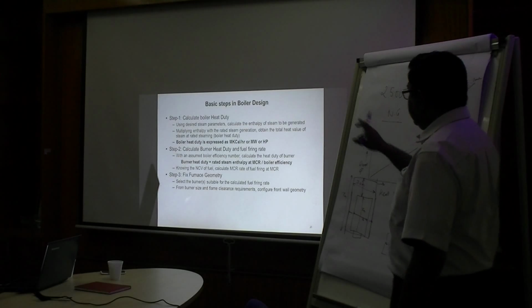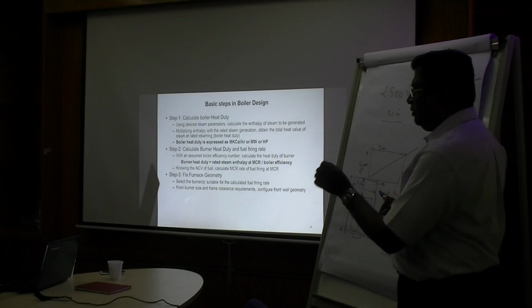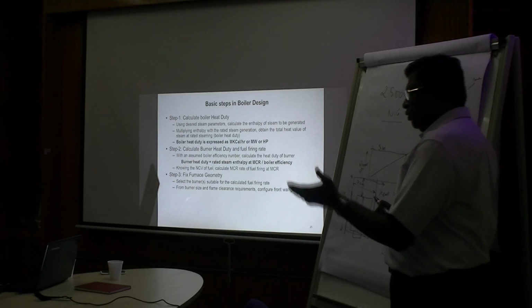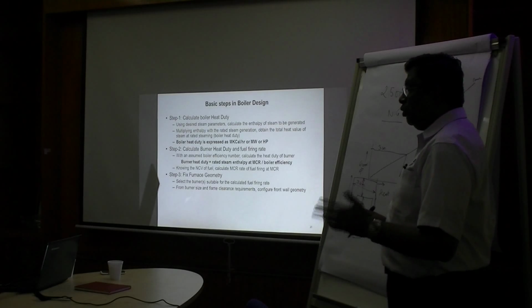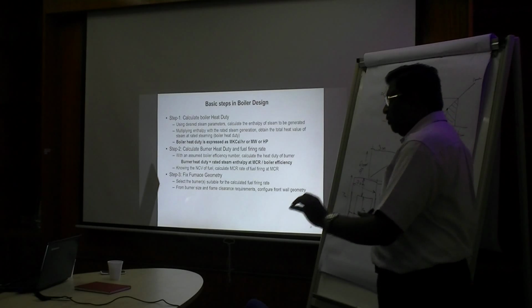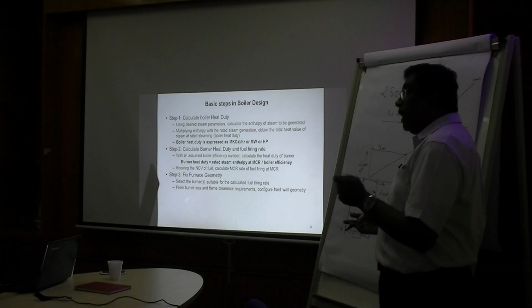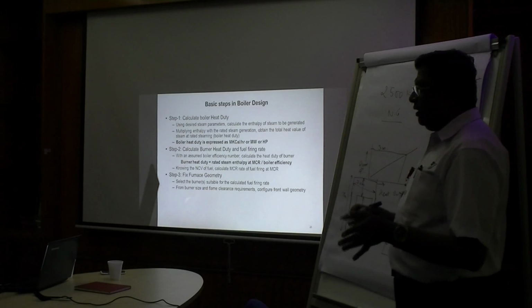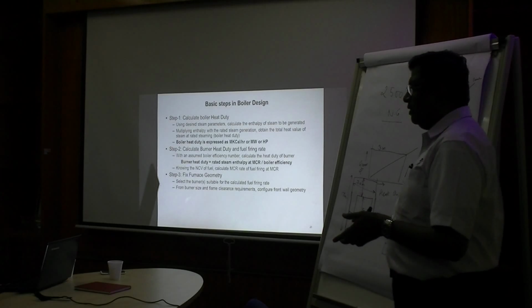And if the heat duty required by the boiler happens to be just at the border point of 2 and 3, a money-making company would have selected 2 burners instead of 3, because he spends less. 2 burners means that many fewer scanners, that much less instrumentation, that many fewer shut-off valves. I thought they are trying to sell more burners. He buys the burner. The boiler maker doesn't make the burner. And at the end of the day, he doesn't tell you that I am selling you more burners, so give me more money.